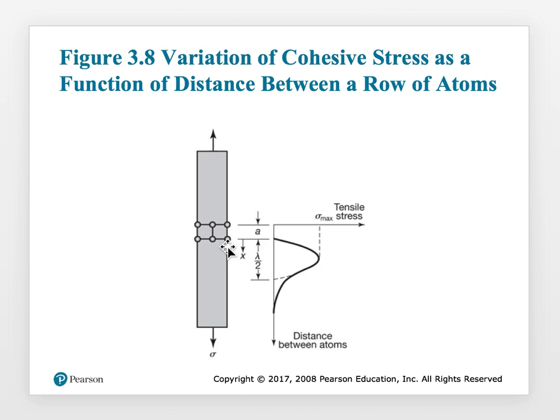Suppose you take a stack of paper. How do you make one set of sheets of paper slide over another set of sheets of paper? You have to shear the one set over the other, and the distance between those planes is the maximum where the plane of atoms have the maximum number of atoms, because it requires the least amount of force to move that one set over the other.